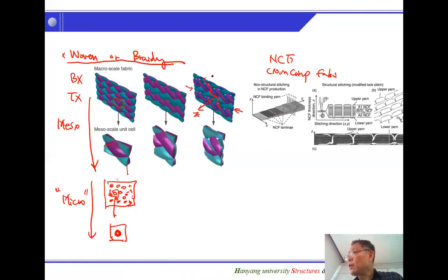That is the very significant drawback of this woven or braiding. Very weak under compression, okay? Because these tows can easily buckle, which will lower the compressive strength. Tension is okay. Tension is not exactly the same as a prepreg type, but say within 5%, that is okay. But compression can be reduced by up to 20 or even 30% of compressive strength, which is not so good.